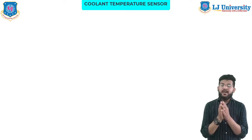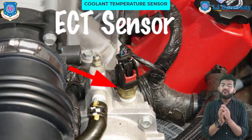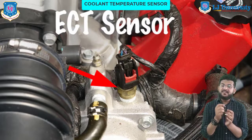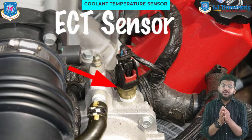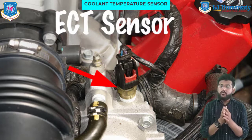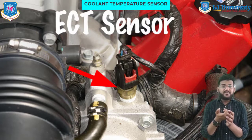So what are the common causes of the failure of this sensor? In most cases the engine temperature sensor fails due to corrosion. This is because of its exposure to the engine coolant, which corrodes it. It may also fail if the coolant leaks through the wiring connectors. So how to spot any faulty coolant temperature sensor?